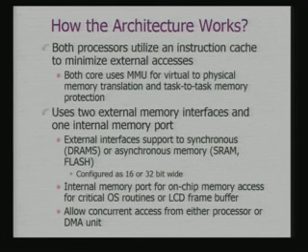Now, how does it access external memory? It uses 2 external memory interfaces and 1 internal memory port. External interfaces support synchronous or asynchronous memory. Synchronous memory like, say, dynamic RAMs, and asynchronous memories which would be flash or static RAM. And actually the program would be resident on static RAM or flash. And there is an internal memory port for on-chip memory access.